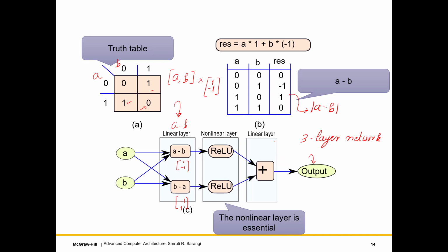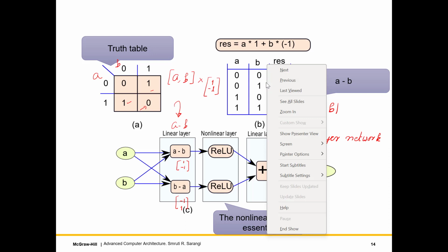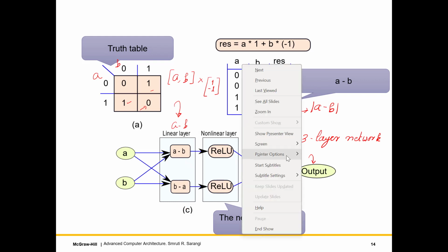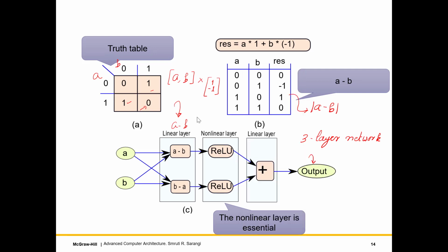So what is the advantage of this network? Well, the advantage can be understood like this. You'll find it is very easy to convert this to an AND gate. Of course, we could do more complex things, but even so, if I simply take A and B and multiply them with half and half, only when both of them are 1 will the sum be equal to 1. Otherwise, the sum will be equal to half, or less than that.